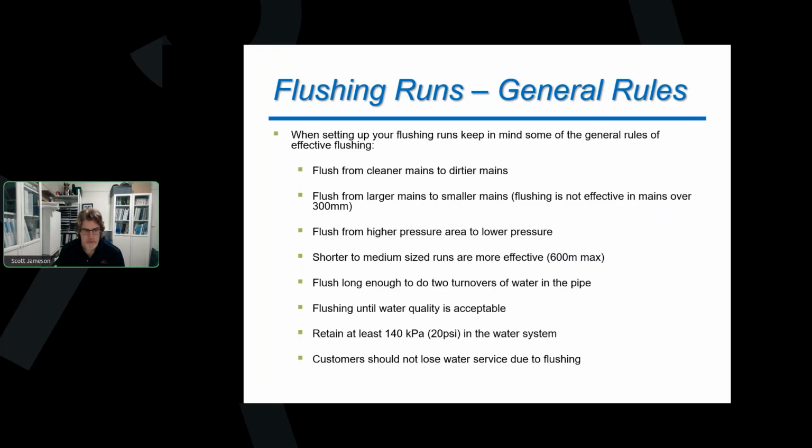And then going down to those last two, right, we want to keep that 140 kPa or that 20 psi in the water system at all times. And no one is out of water while we're doing the flushing program. So if we can answer all those questions on the desk while we have planned things out, hopefully when we go out into the field, we can confirm that all those things are correct.